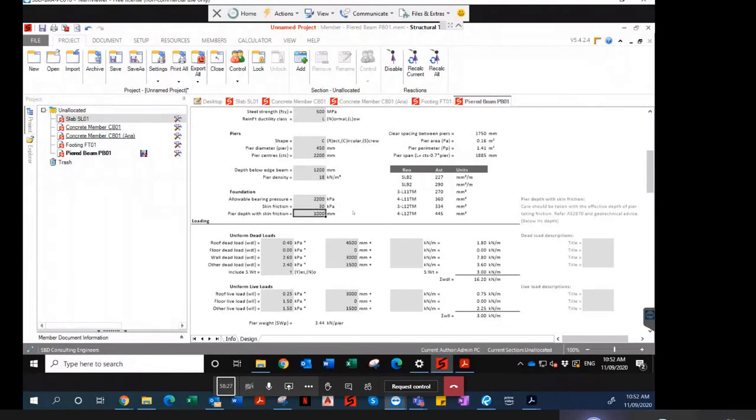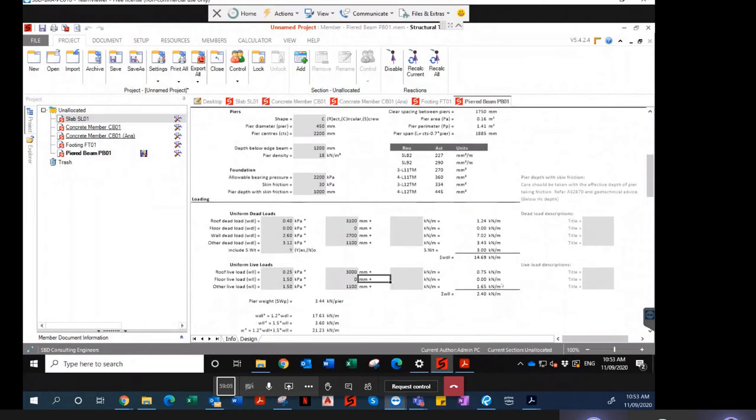That other dead load that you have put, 2.4 by 1.5. Yep. That's from where, that load 2.4 kPa? So you used 3.12 in there, and your slab is 1100, and use 3.1 and 2700. Yeah, 14.69. It's pretty close.